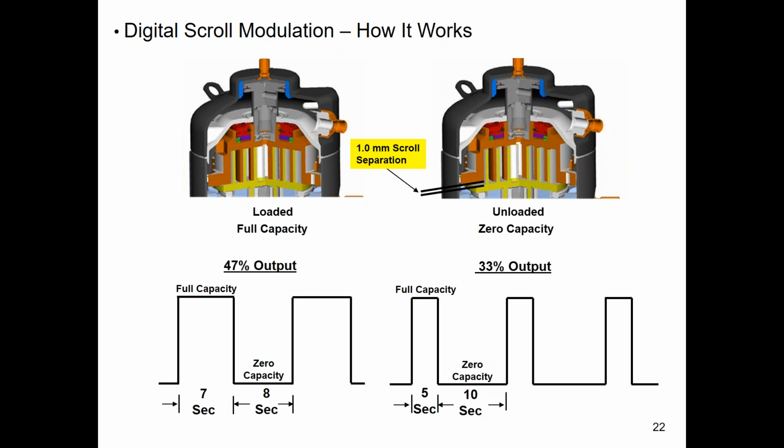So you start this one up, you lose oil out of it, you go through the same thing, lose that compressor. Now the third compressor, you've got even more oil in the system. It gets worse and worse, and you can tell those jobs because your compressor duration, how long they last, gets shorter and shorter and shorter. You have to correct the installation. You can't have buried pipe. If it's there, good luck. I would look for a different route.